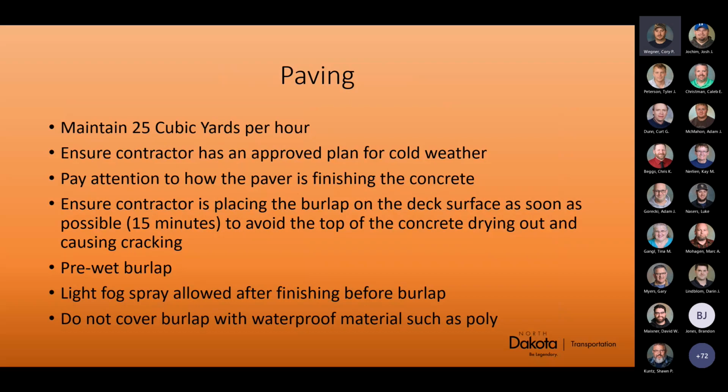If there's cold weather expected, we live in North Dakota and it seems like our construction seasons get shorter and shorter every year, so just make sure they have a plan for cold weather, especially for the deck pour. You don't want to run into an instance where your deck freezes. Pay attention to how the paver's finishing the concrete. I'll show you a slide here in a minute that has some things that I noticed last year.